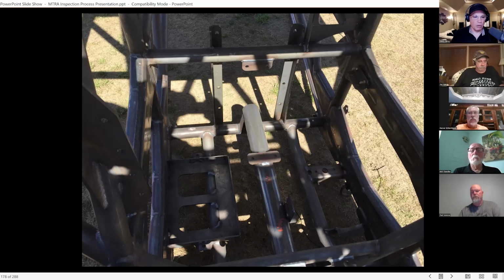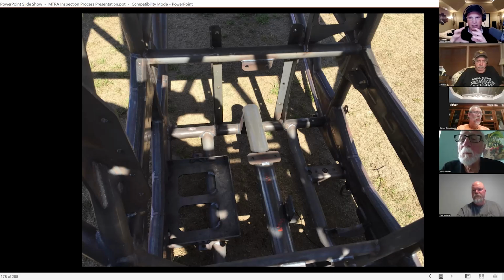Some older trucks might have an actual carrier shaft, which is a portion of a drive shaft that will have a U-joint at the transfer case end, and then it goes to the carrier bearing. Sometimes they'll have a rubber horseshoe with a rubber isolator in there. But most modern trucks now will run a spline shaft.